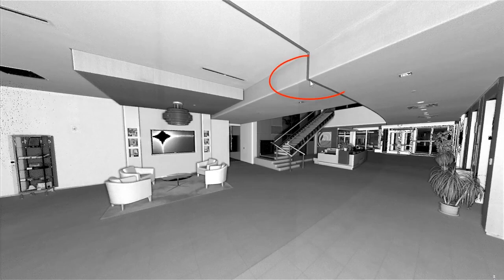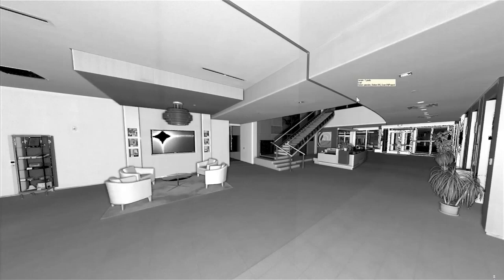And again, plenty of data to model it or create a floor plan. But if I look at that same area with the stationary scanner, you can see I pick up more detail like the molding and the intersection between these panels. So if you're looking for the detail, maybe needing to find sprinklers or anything located in the ceiling, again, you'll want to look at maybe a stationary scanner. But if you just need a quick floor plan or a map, a handheld scanner would go very nicely.